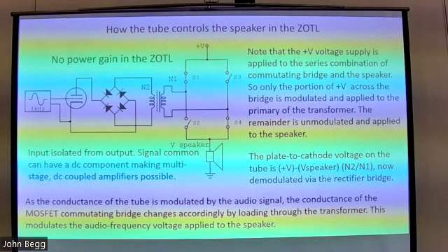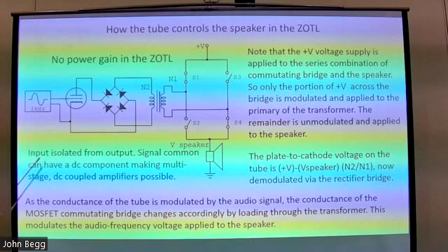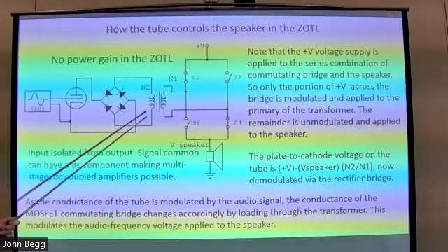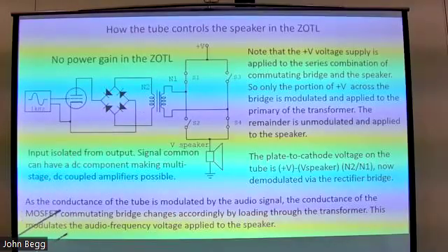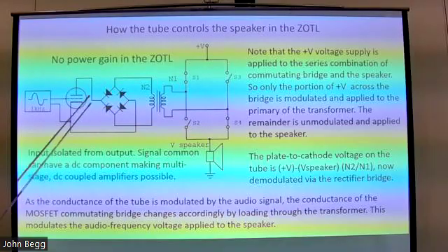And I do that all the time in my amplifier designs because I want DC coupling, and I have cascaded stages, and by the time you get to the grid of the output tube, you want to be up at 300 volts or what have you. So this allows you to do that, and yet you get DC coupling through this scheme of modulation. So this is a DC coupled amplifier, but you have this isolation for DC where you want it. So that's a nice feature.